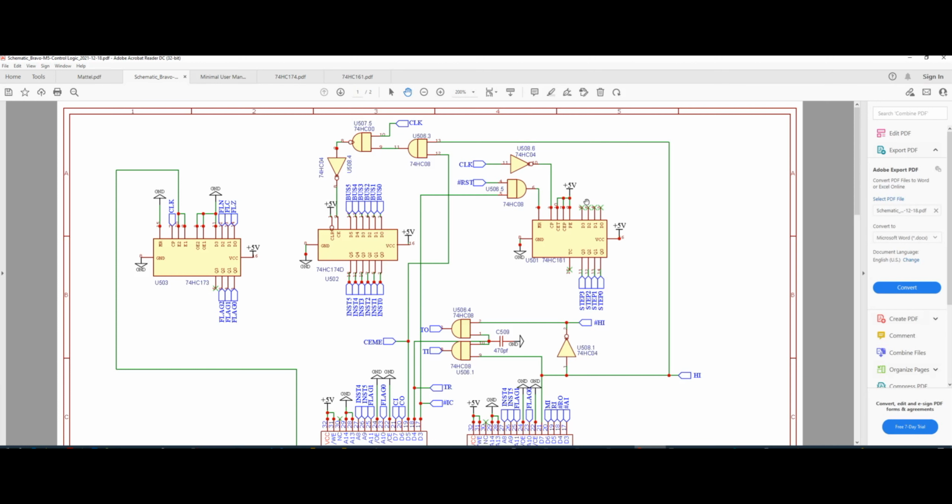And finally, we have the microstep counter, which is again very simple. It's a 4-bit binary counter using a 74HC161, and we have talked a lot about this chip in this project. And as you can see, all the input lines are tied to nothing, or basically no connect. And then the output of this chip will be really just a value between 0 and 15.